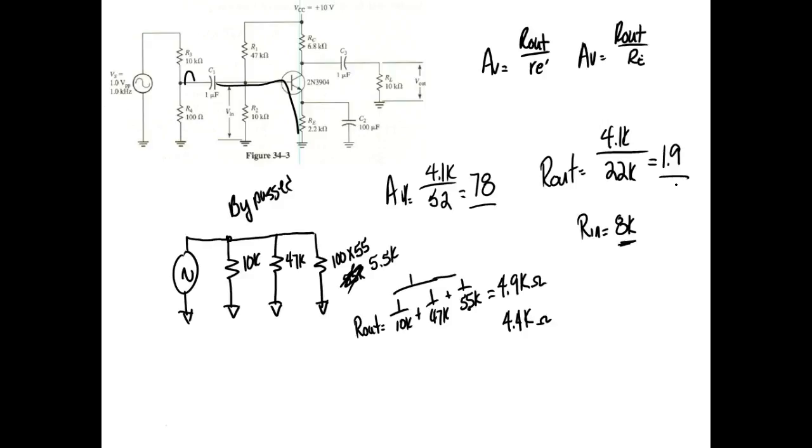But now I've got a gain of 2, and I've got a current amplifier now, right? This guy amplifies current. So I could take this gain of 2 and my next amplifier might be bypassed. When I hook this up to my signal source, it's always going to have an impedance, or a resistance to it, right? And if we put current through a resistance, we get a drop.